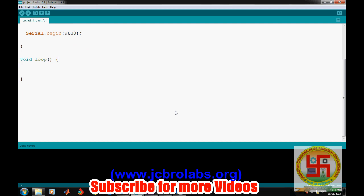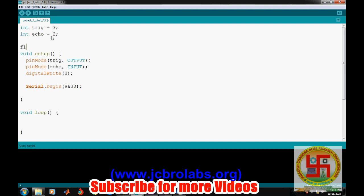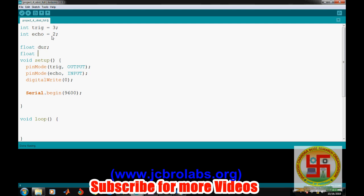Now in this project we will use functions. Functions are very similar to those we used to create in C language. The only flexibility is that we don't have to provide the prototype or the signature of the function at the start, so we can start writing a function from anywhere. We will create a function, calculateDistance, and it should return the distance calculated by the sensor. So we will make it a float return type. Prior to it, let's create two variables, float duration, because it will calculate the duration of the pulse, and then distance.